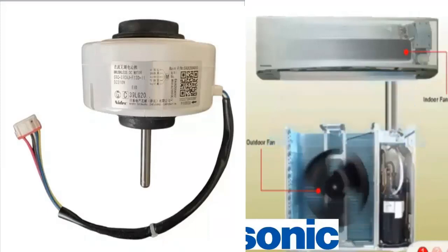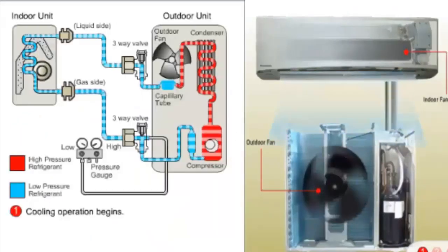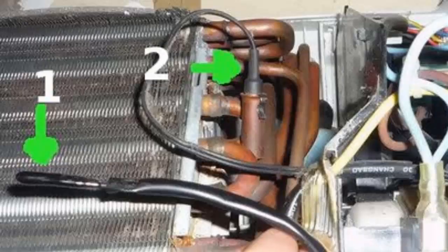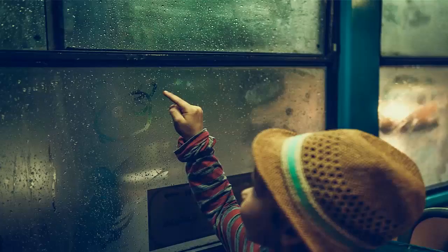B. Low airflow due to a dirty air filter, causing airflow obstruction. You should clean the indoor unit's air filters. C. Poorly placed evaporator sensor, preventing the unit from shutting down due to freezing.